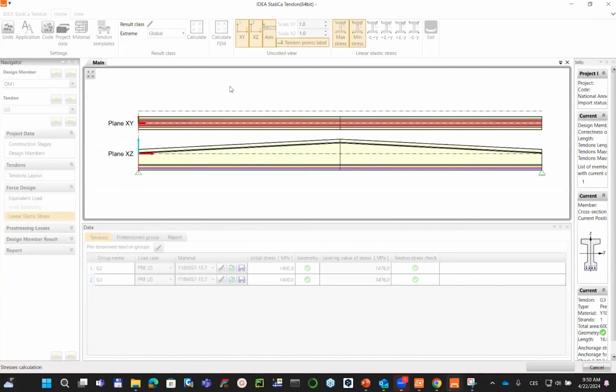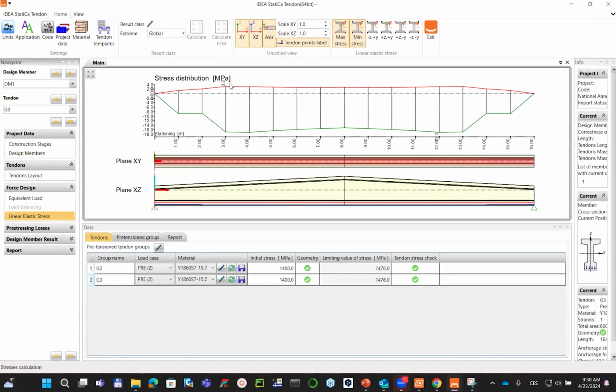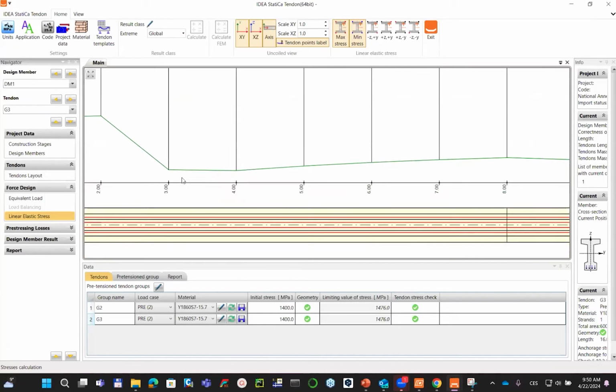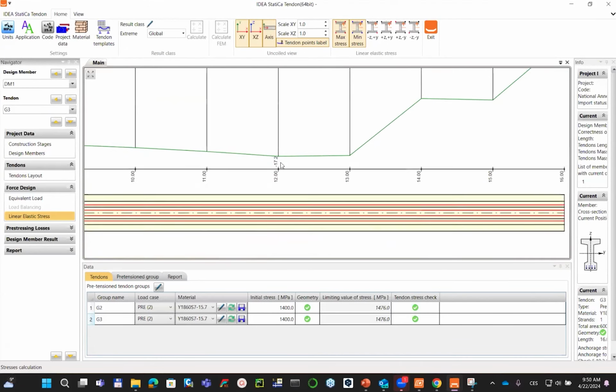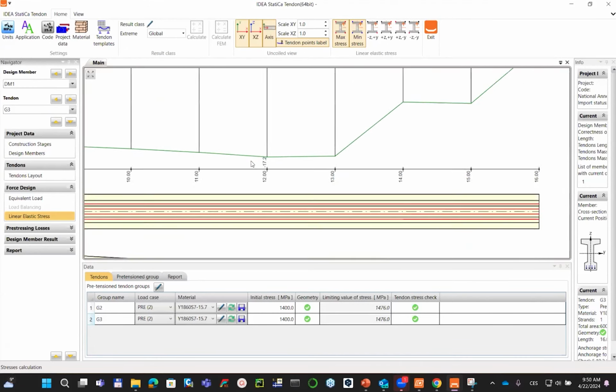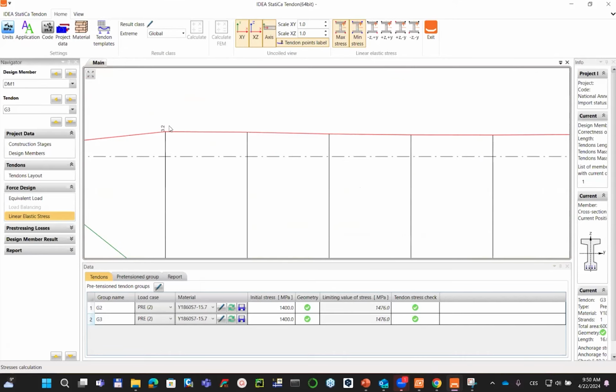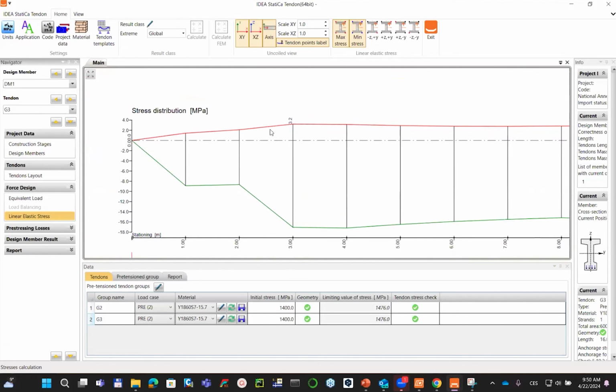This is like a pre-designed tool that will help you to identify where the maximum stress is and what is the magnitude. So if I check, this is my envelope of the stresses. So I can see that the maximum stress here is 17.2 megapascal. So I think it's feasible. And the tension stress in the top fibers is 3.2 megapascal.